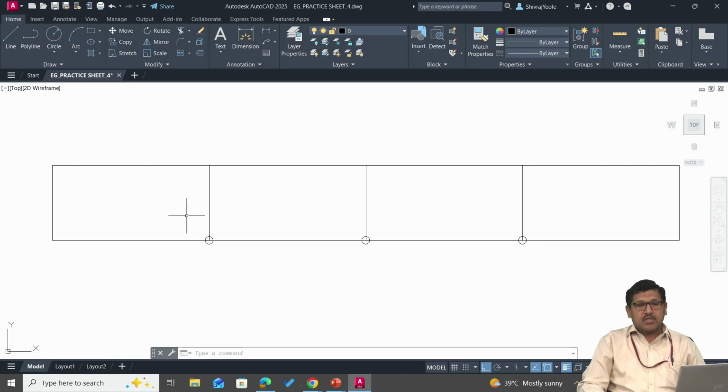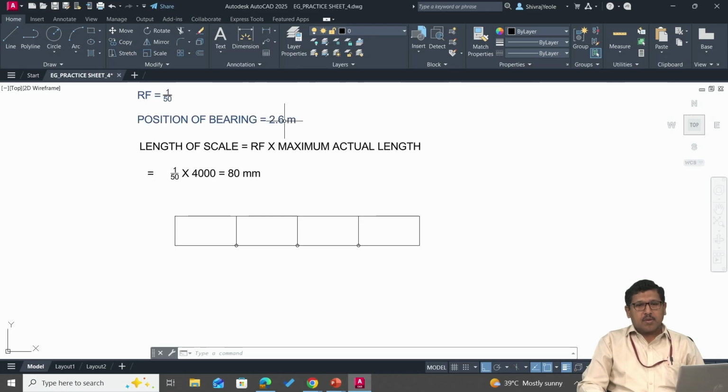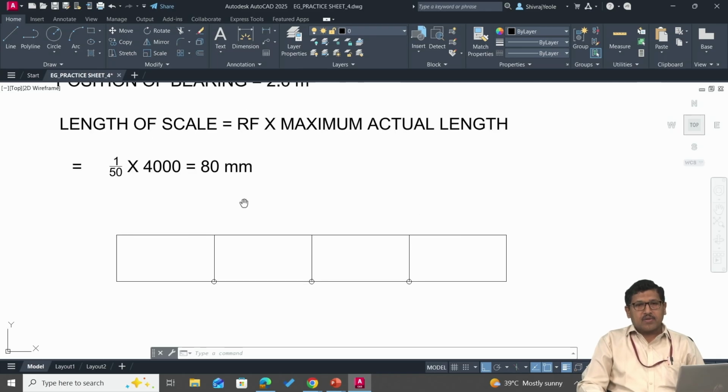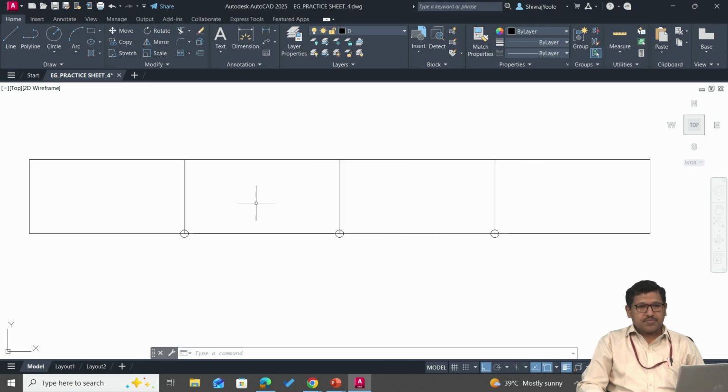The next step is we need to divide the very first division into some number of parts. So what is the number of parts here? So it is nothing but the subdivision. So if the main unit is meters, then we need to go for its subdivision. Now we have been asked to show this 2.6 meters length on the scale. So that means we should be able to show that 0.6 meters also in this scale. So for that purpose, the first main division will be divided into 10 parts.